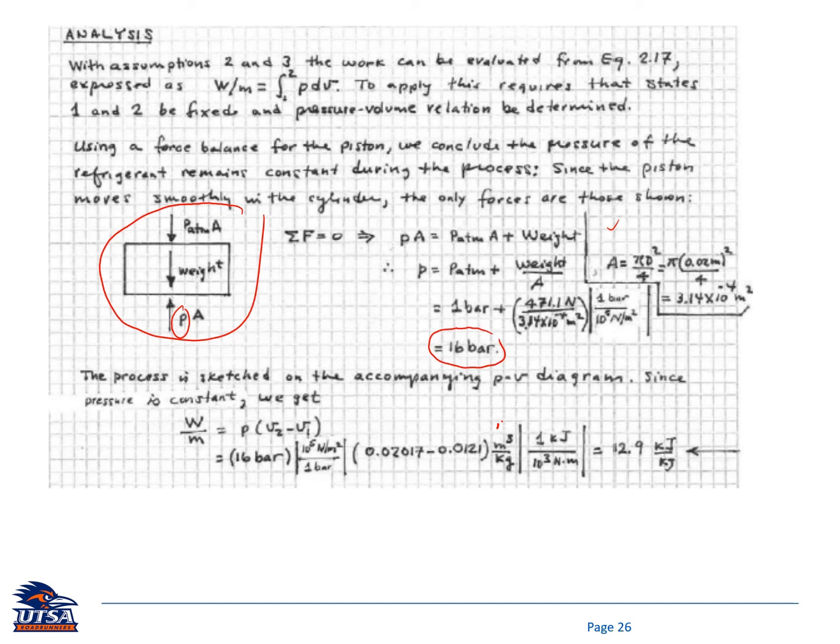Saturated vapor with a given pressure, so then you need to go to table A3, right? You need to go to table A3 to get what is V1 there. What is V1 there? Okay, so once you have V1,